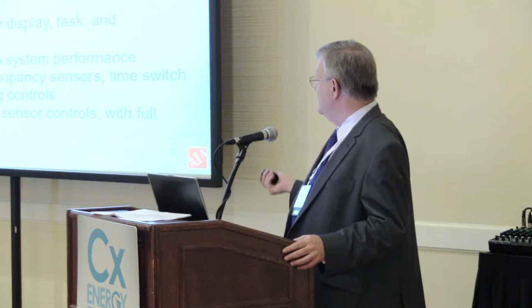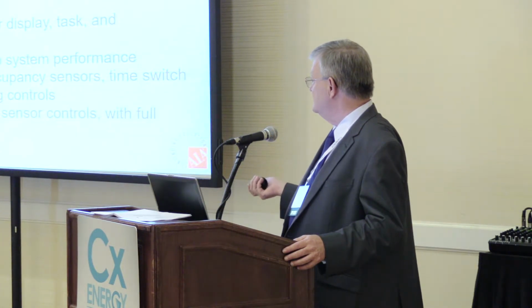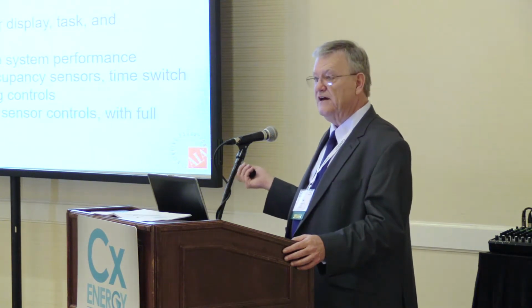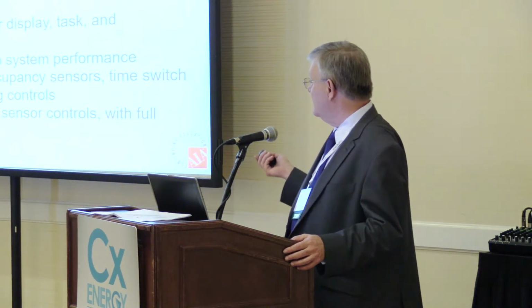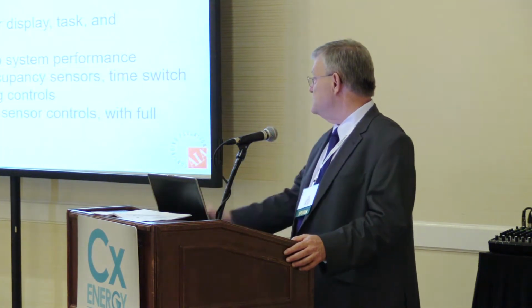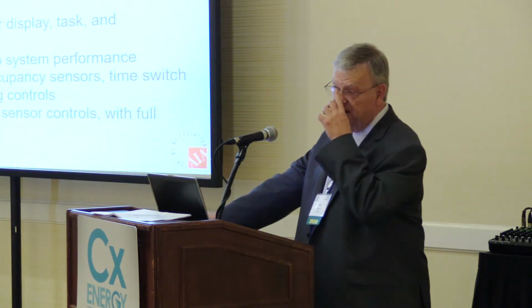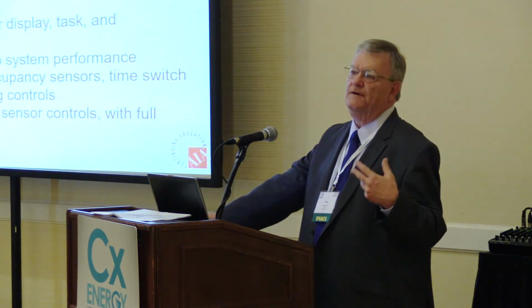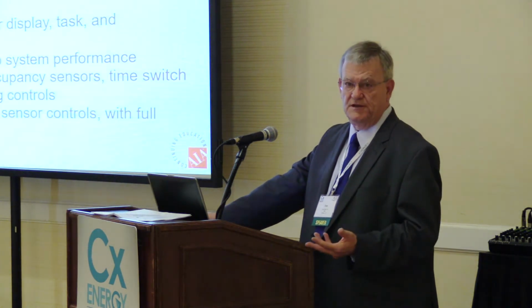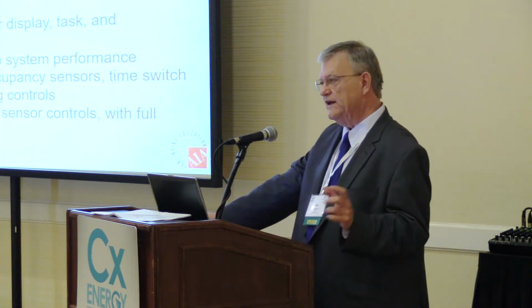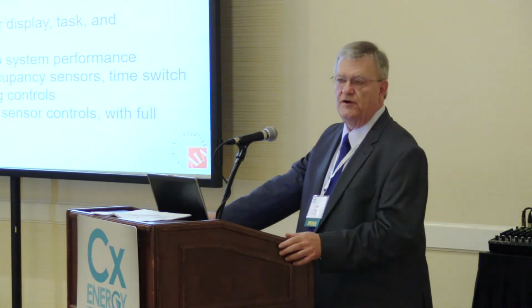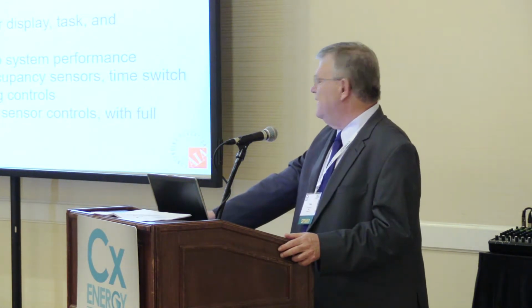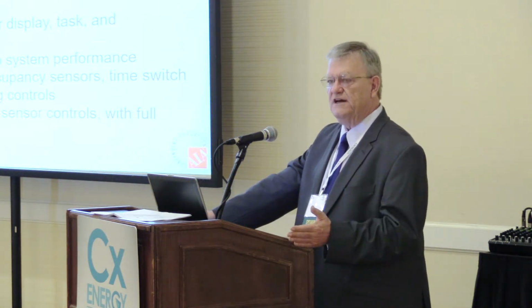It has detailed requirements for occupancy sensors, time switch controls, daylight sensing controls, and the testing requirements are substantially like the ASHRAE 2013, so we're not going to go through them all again. And finally, and this one's interesting to people who are electrical contractors, 10% of the occupancy sensor controls have to be tested, either all of them or 10% of the controls, at least 7, depending on the size of the project. If you're working on a large project, you'll be doing 10%. And if 30% of them fail, you have to test every single one.